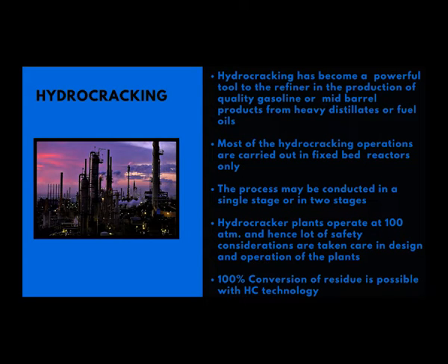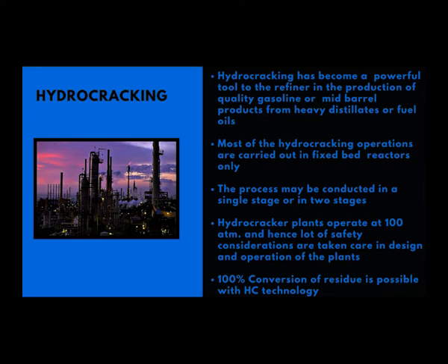While in the previous case the catalyst is in a fluidized state, and it is known as a fluidized bed reactor, in a hydrocracker unit the reactor bed is solid and fixed, like a hydrodesulfurizing unit. This process may be conducted in single stage or double stages. The hydrocracker plants operate at more than 100 atmospheres, and a lot of safety considerations are put in place to address any kind of eventuality.